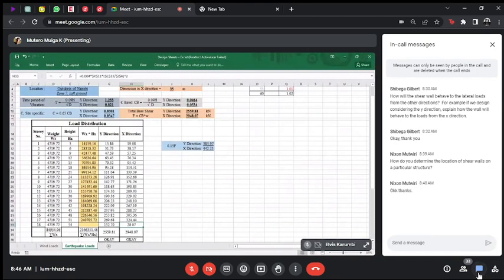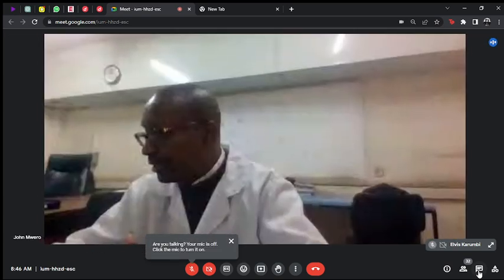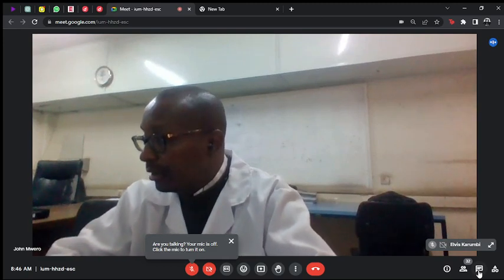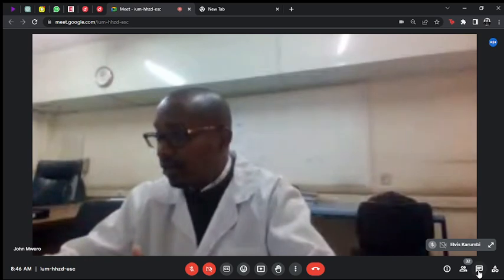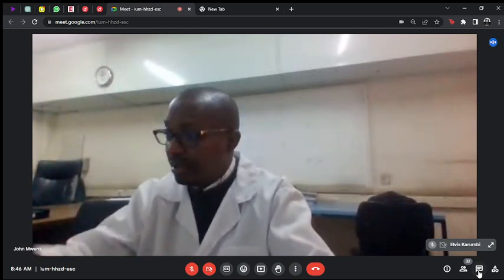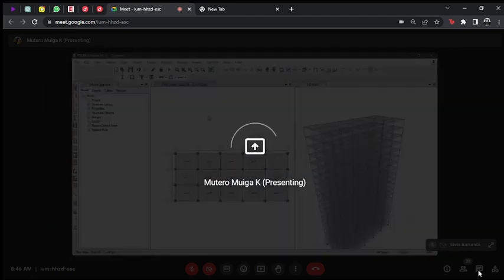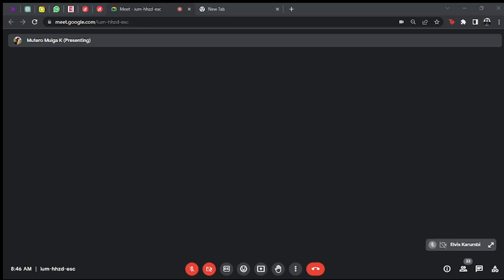If you can find time, pick for example the Eurocode, because our country is moving to the Eurocode. Pick the Eurocode and see what it says about the wind. If you like, you could do a parallel analysis for wind, a separate spreadsheet for wind to Eurocode. So we have wind to CP3 and wind to Eurocode.